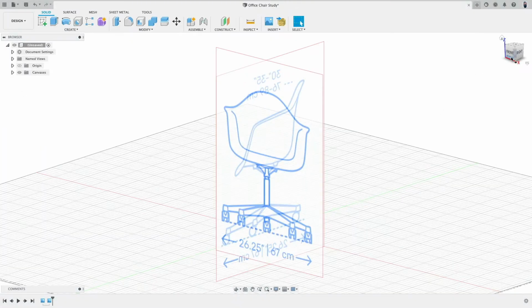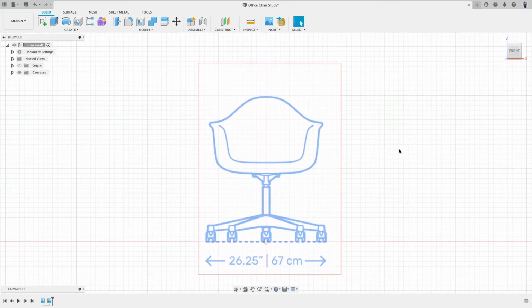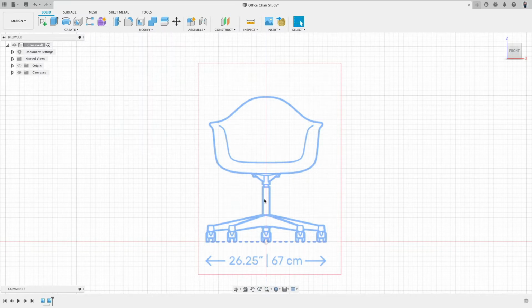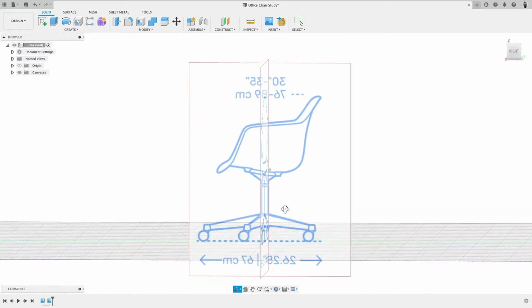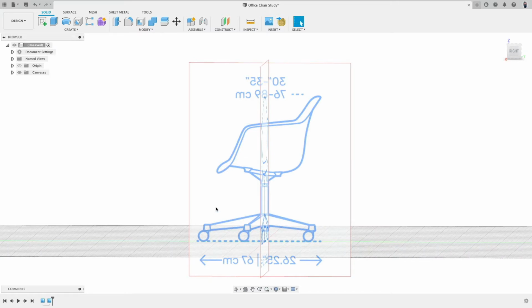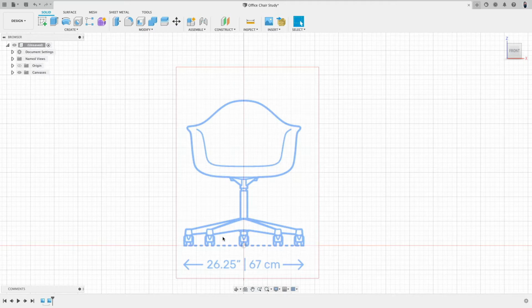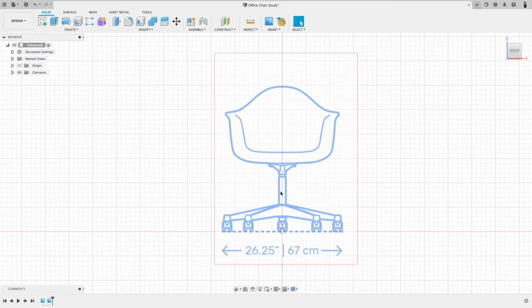Very good. Now, since we would like to quickly explore various shape styles for the seating using the sculpt or the form environment, we should first create a basic base everything will be sitting on. And this reference image actually has casters in it and a 5-star base. We will do everything without the casters, but we can use the rest as a proportional guide.